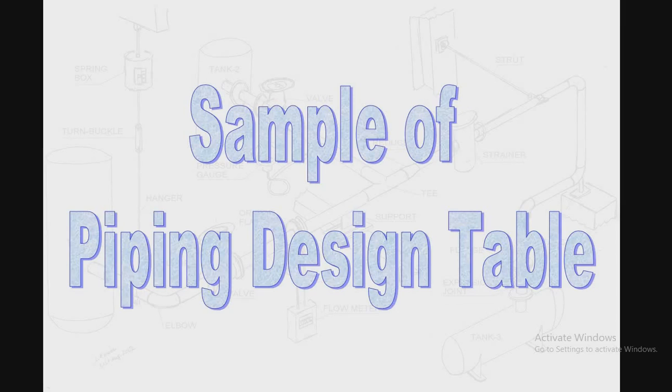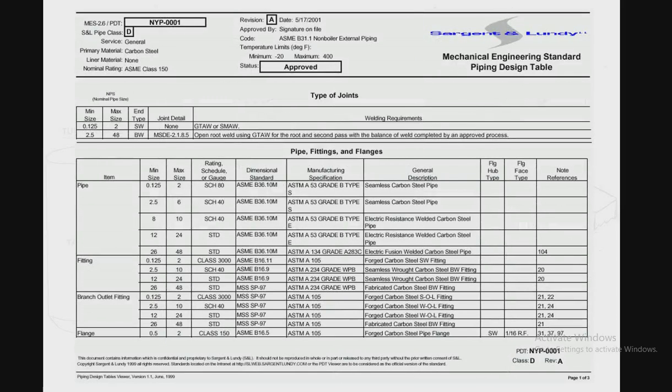Now we will show a sample for PDT. It's a sample for piping design table. Here we see the PDT for the project, specified for project, service and line material, liner material, nominal rating according to ASME class 150. Here we see minimum size, maximum size, the type butt weld or socket weld, joint detail, welding requirement, process detail.